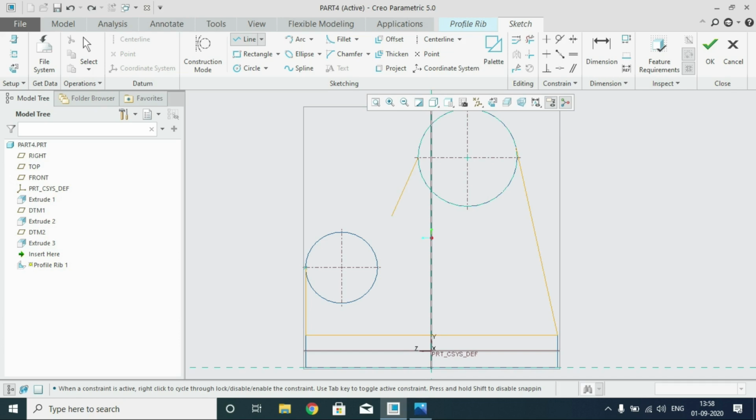Let us see. Okay, it is drawing a solid line. So go to construction mode, then draw a line. Okay, now track. Either we start from here and then we'll track. Then go about it. Is it horizontal? Yes. Now we'll draw the line. You have to come out of construction mode, then go about drawing a solid line.